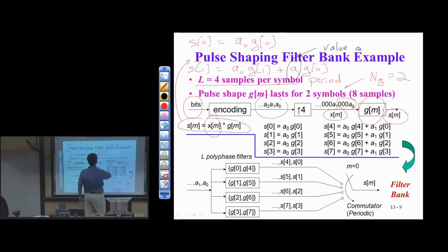Oh, this is an A1. I'm sorry, this is not A1. That's what the confusion is. All right, this is X. So this is convolution of X and G. So I have X 0, now I have X 0, X 1. Sorry about that. And that has value of 0. So I'm wasting the computation, because I know the structure of the input signal into my FIR filter, and I can take advantage of that.